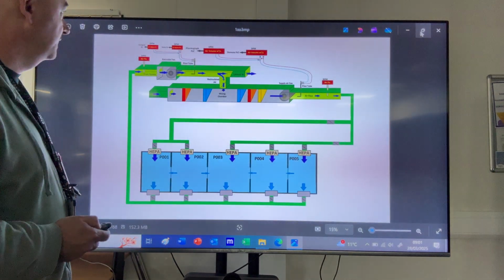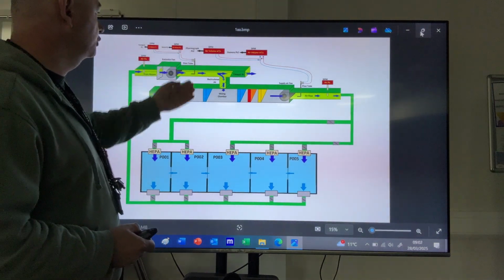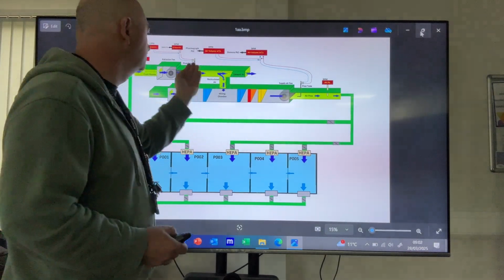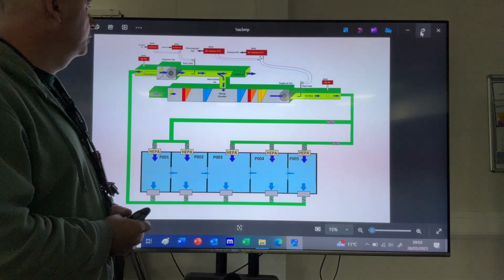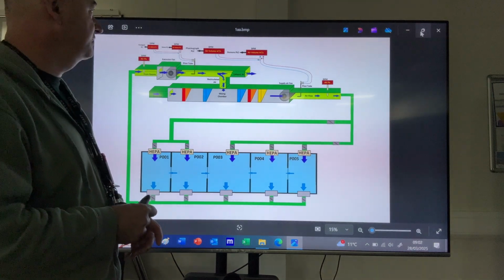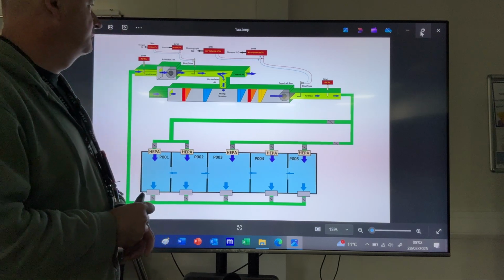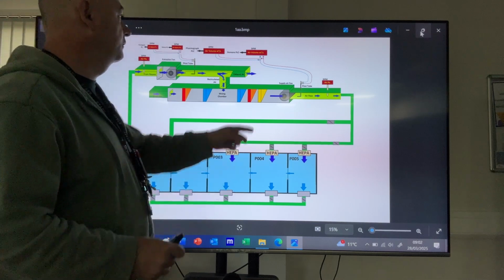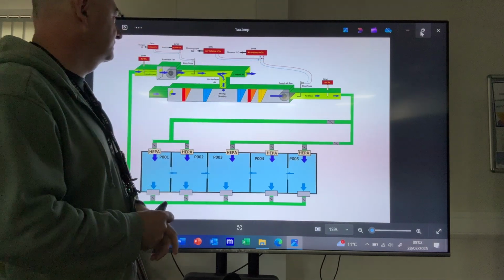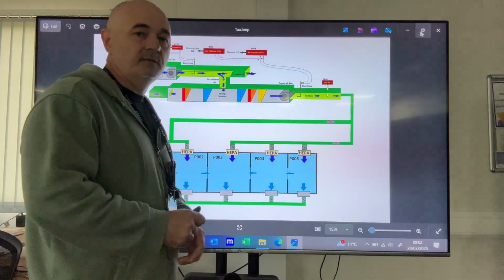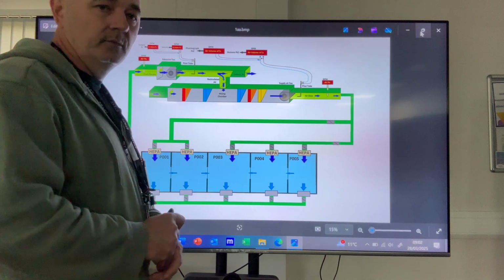You have a better view of the AHUs. What we have here, we have pitot tubes inside the duct, and these pitot tubes will only send the airflow data to the SCADA. I pulled a conclusion that if I use a T onto these tubes, which come from the pitot tubes, I can send data to another DPM, which could send data to the Pharma graph. So then I have a legitimate monitoring of the global airflow